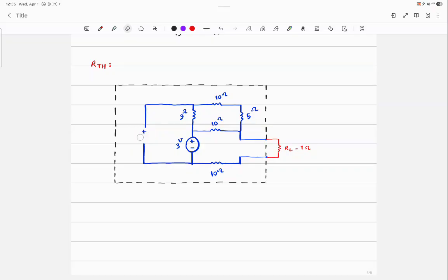Yeah, first of all, kill the voltage sources and current sources if you have. Replace them with short circuit. Something else. You actually asked the question. In my setup, RL shouldn't be a part of that, okay? RL is not your concern. So remove that.